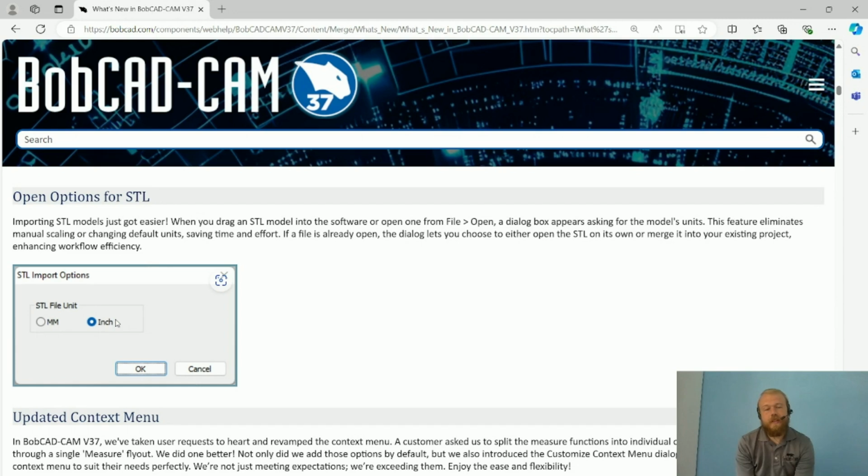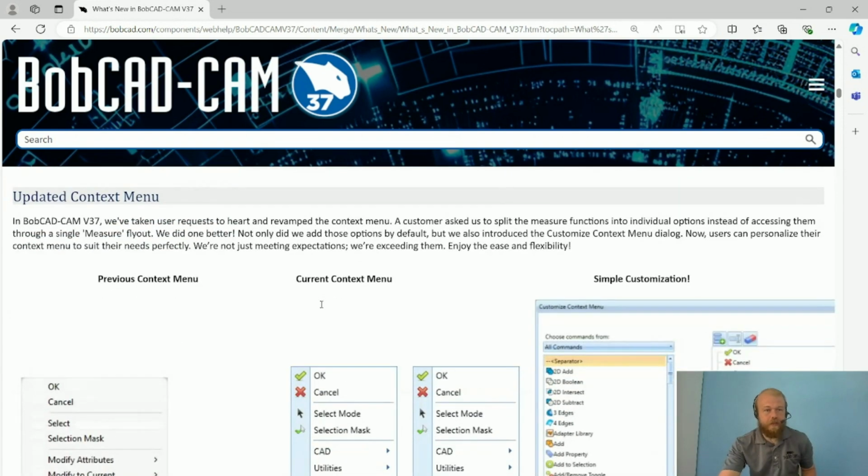So you have the selection here to change that scaling up or scale it down. So sometimes when you open up a part file and it is huge, 25 times larger than you're expecting, you can just change it to millimeter there, and it will change the scaling for you automatically, so you don't have to scale it down manually.